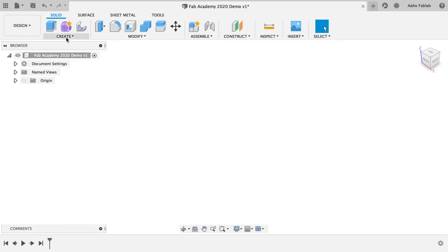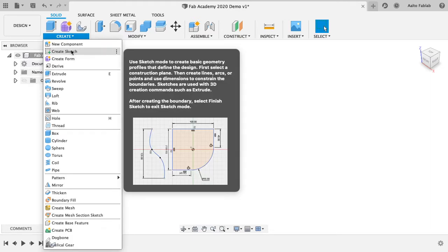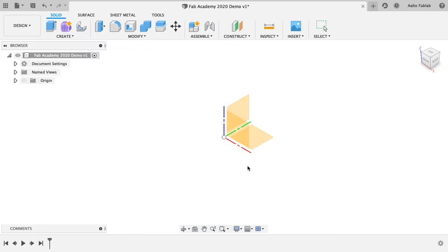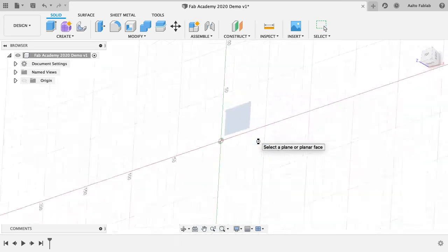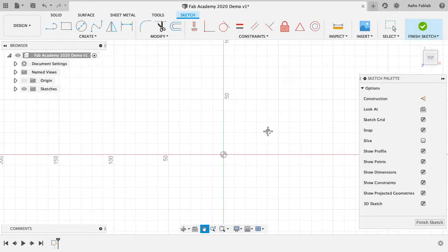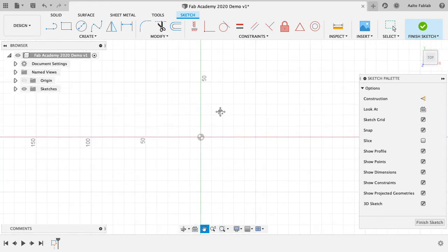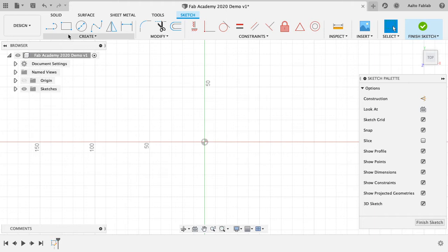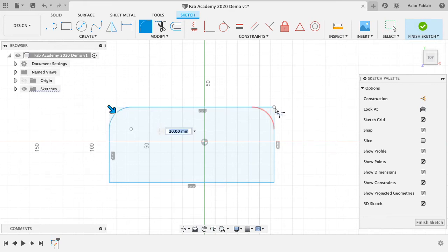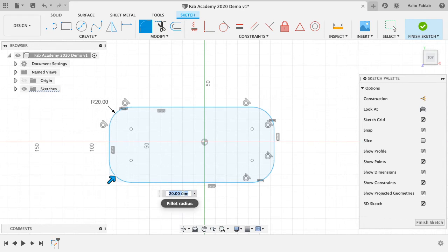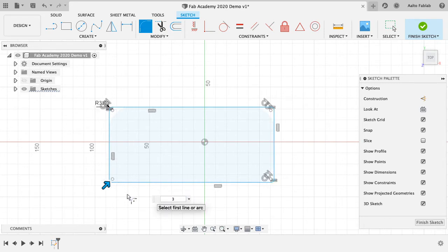Nice. So here, when you click on Create, you can start with creating a sketch. And to create a sketch, you need to choose a plane. So I'm going to choose a plane in between X and Y axis, like this, so that I can pan with the middle mouse button. And usually what I do is specify a rectangle. And if we want to have fillets, then I right away create the fillets. And for the fillets, it's nice to know the corner radius, which is going to be 3.